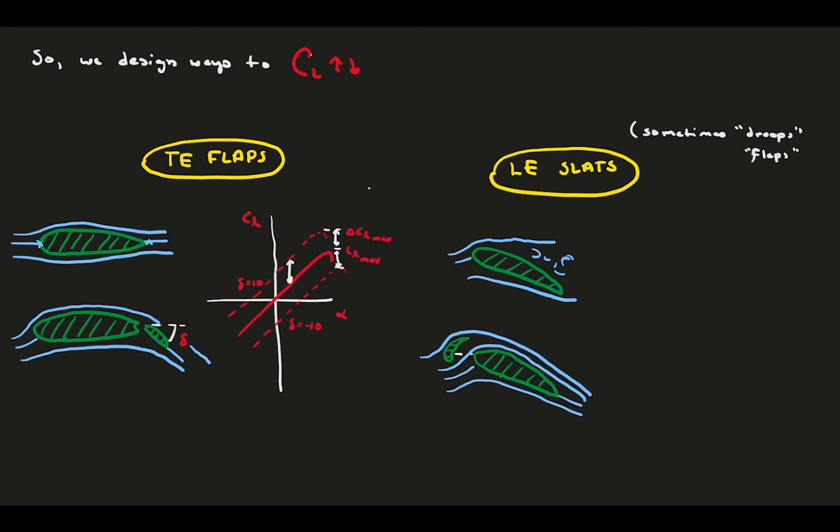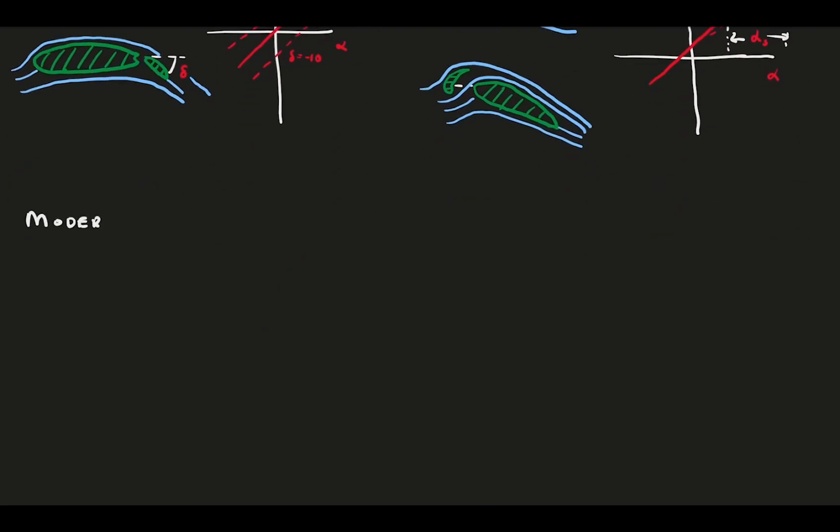This is because the slat allows flow through the foil and acts as a pressure relief where the flow is most likely to separate. Drawing the lift curve for this situation, the solid line represents the foil without the slat activated, and the dashed line represents with the slat. What we notice is that the slat significantly improves our angle of attack range before separation and also leads to much higher lift coefficient. Both of these technologies are utilized in modern airfoil designs, but to a super engineered level.